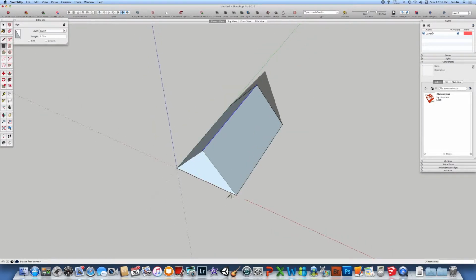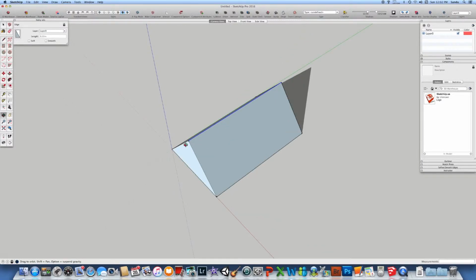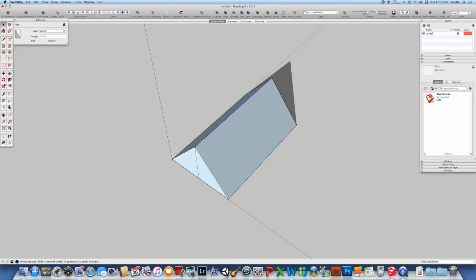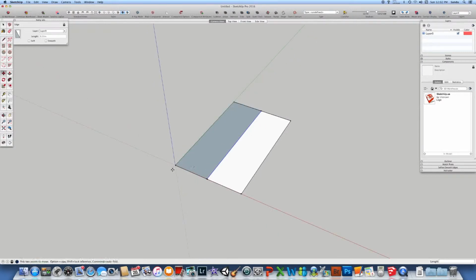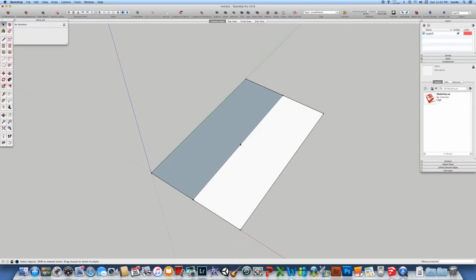Now, let's say you want to have this a little bit more complex. So let's say we have the gables, and also a roof cut in, let's say, at 45 degrees. In that particular case, let's move back that line. Basically, we can just move this down. So we'll select the line, and after that we move it. And again, it's no difference. Basically, we have a plan view of the roof.